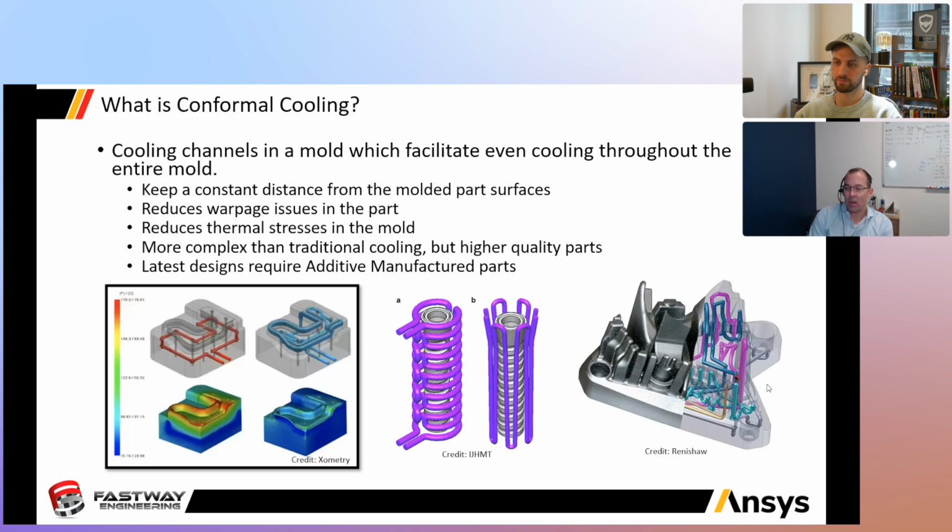Those cooling circuits not only have different lengths and different locations, they get different diameters. So now what they've done is truly optimized. If somebody did their homework, and it looks like they did, this mold could be operating within maybe just a few degrees of each other across the whole mold. So really, really incredible stuff. Something we weren't able to really do, and the limitation really was just the fabrication method of the mold.